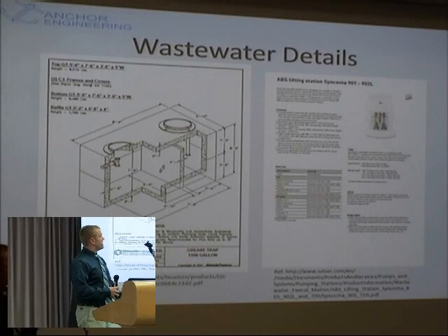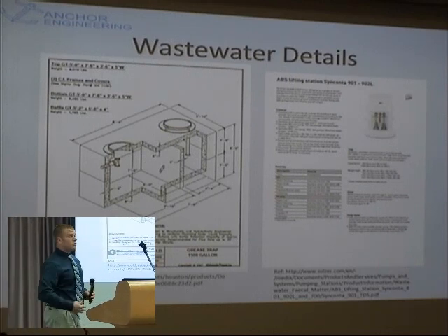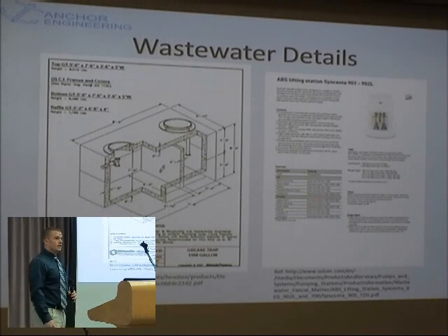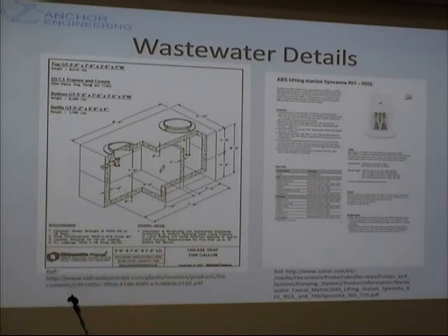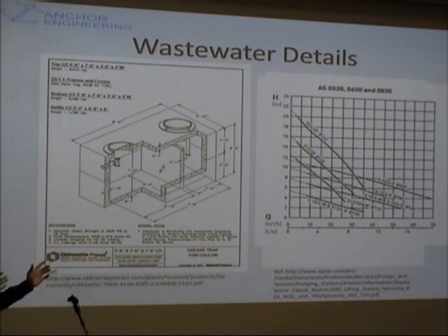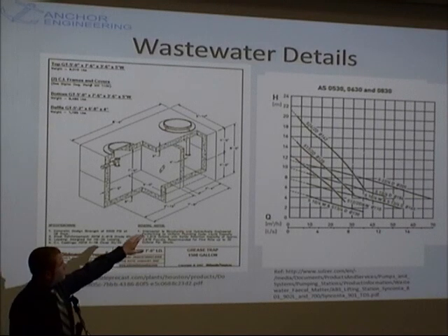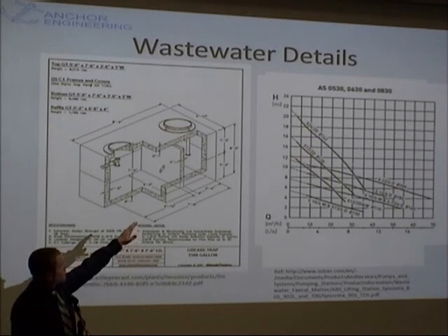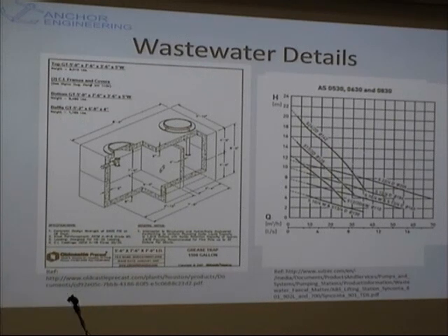On the right, we have the pump detail that I selected. It's a fairly large pump. It was one of the larger ones the company offered. It has to deal with, again, overcoming such a large elevation change. The pump manufacturer provides you with a pump curve, in which I had to impose the system capacity curve. We can see, as we have a high head over on the left side, that's where our capacity curve lies, which is on the largest pump on that plot.